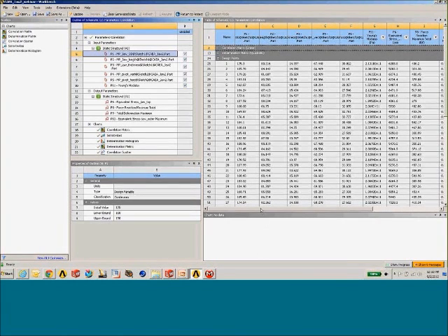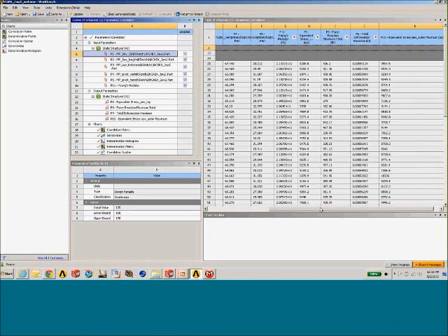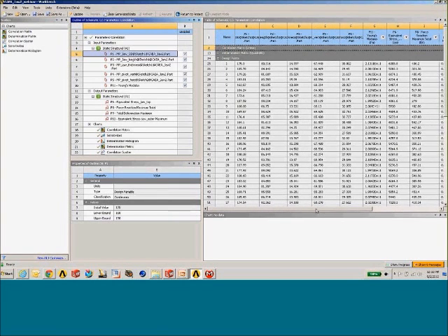So if you want to kick off this solution, walk away, come back, you'll see which of those points you were not able to regenerate, and you can go back, figure out why that's not occurring on the CAD side, or adjust your parameter ranges accordingly. So it's a quick and easy way to determine whether or not you're going to get all of your design point solutions before you go into the design of experiments aspect of the problem.